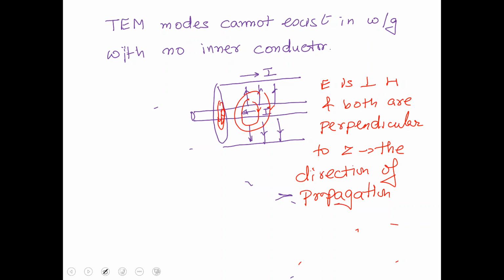So basically, you defined a circuit model which was an LC circuit, which was coupled oscillators, and thus you came up with a wave equation. In reality, if you actually go and calculate the fields inside, what you would get in this coax cable is a TEM mode.